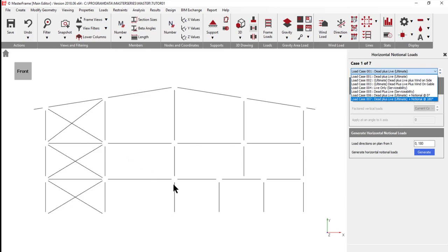It does it in two directions because the frame is asymmetrical, so therefore you're always better to do it in the two opposite directions. So we'll be able to use that later on to check our frame stability, or lambda crit values. So before we go and analyze, we just need to look at the continuity of the joints. We're going to pin some members.